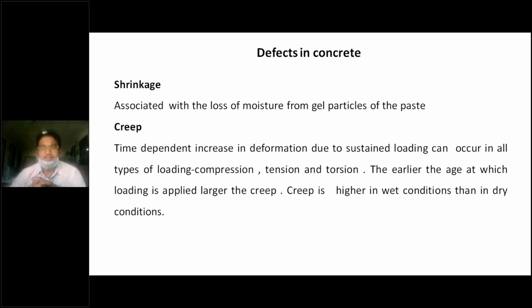Okay, so when you go with high grade of concrete, definitely you can have very less shrinkage. That is the reason why we are making use of high grade concretes in prestressing technology. And coming to creep, we all know it's a time dependent one. When the time goes on, it increases in deformation with a sustained load.